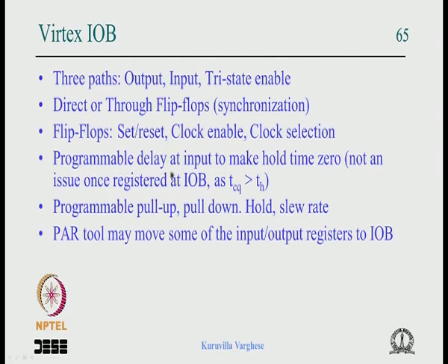Programmable delay can make the setup time 0, sorry, hold time 0. You have the programmable pull up, pull down, hold and slew rate, all that is programmable. Okay, you can program it.